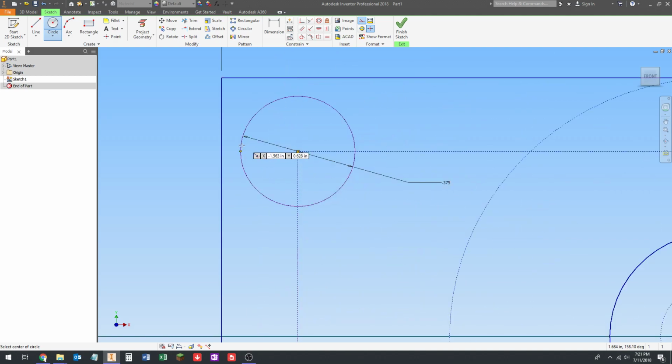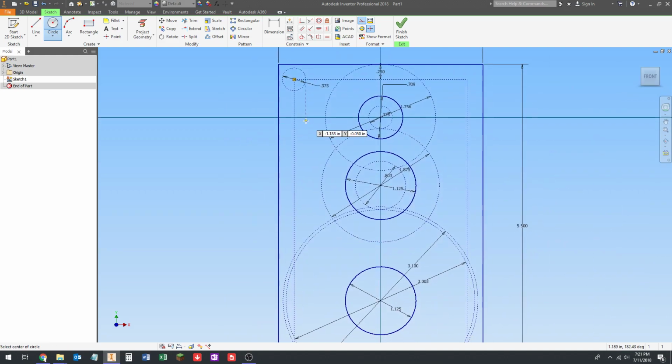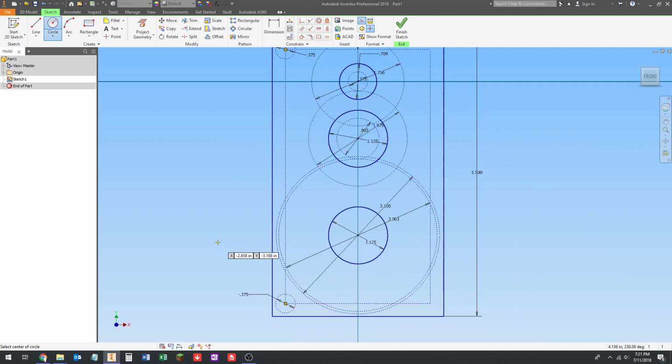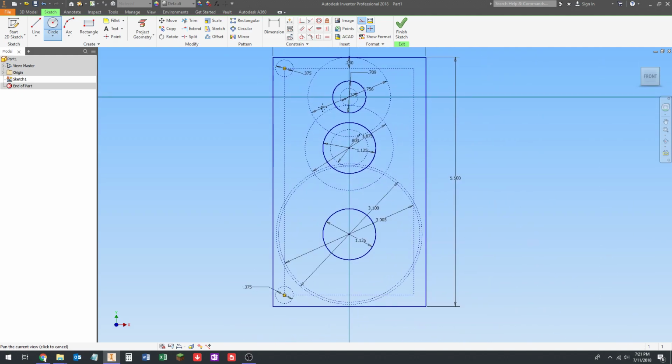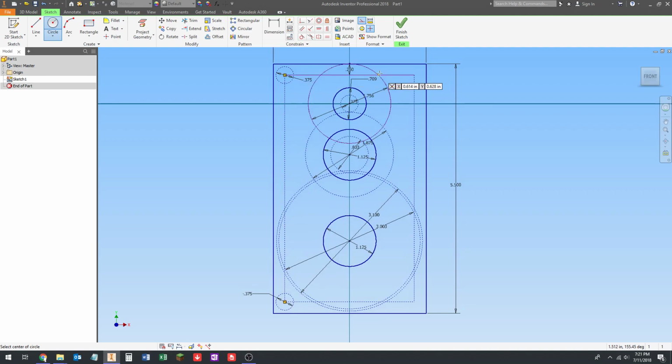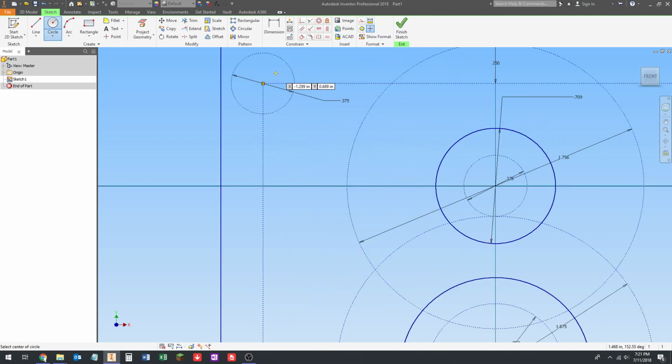Now, I know for a fact the screw head that goes into this is smaller than the diameter of the standoff. So if it clears the standoff, it clears the screw head. But in certain cases, you need to be worried about screw heads as well. So that's what we got. We know we're good. So what we're going to do now is we're going to draw circles that represent holes. So I'm going to turn off construction geometry here, and I'm going to draw another set of circles.